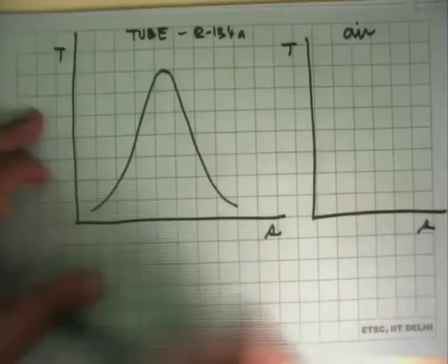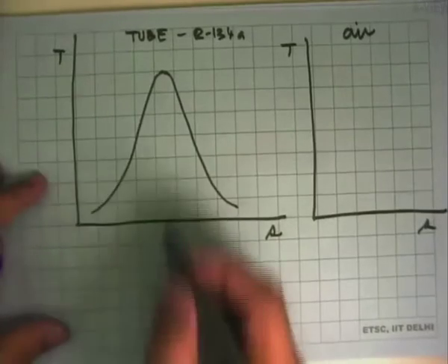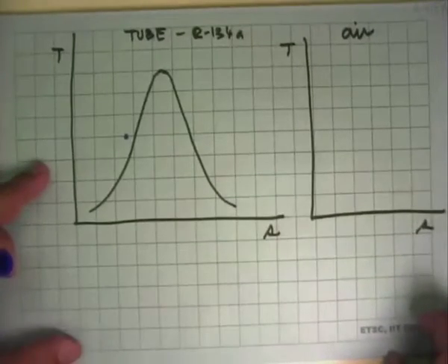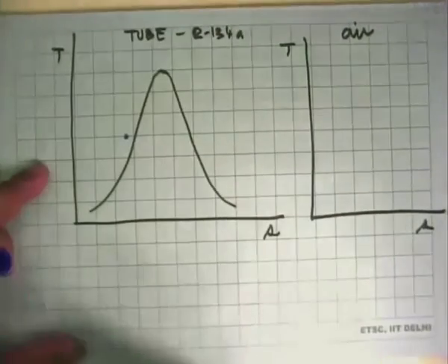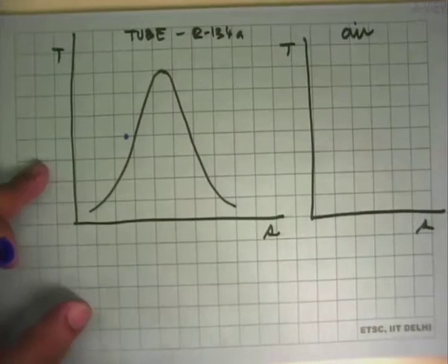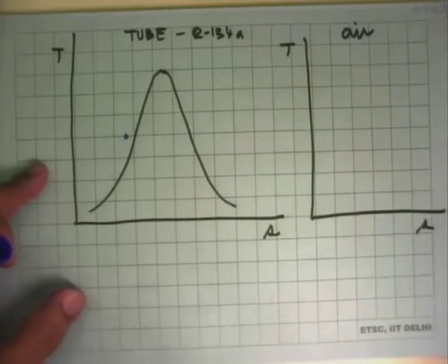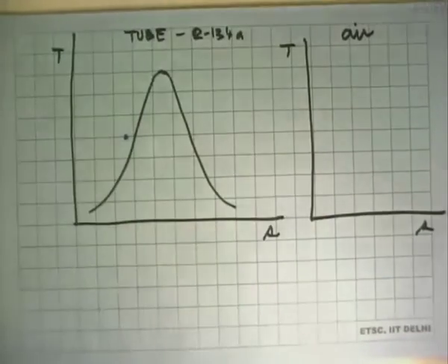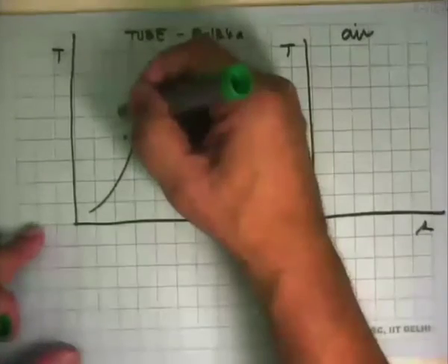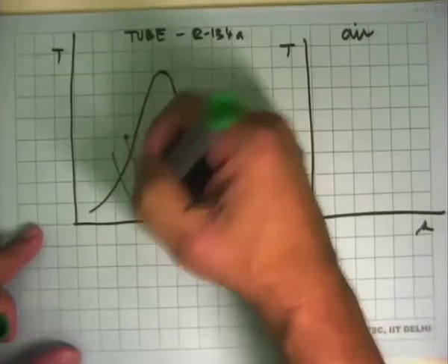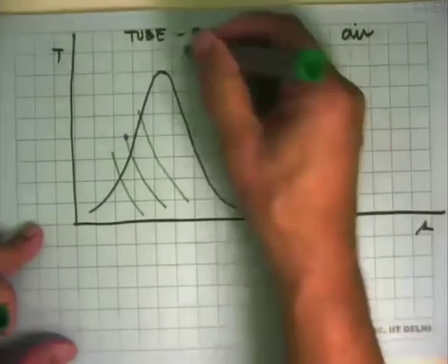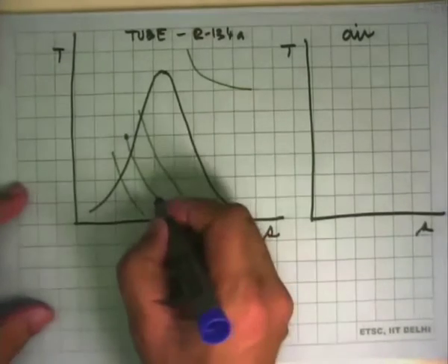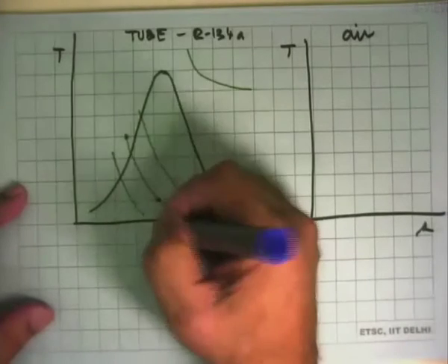So in this case, what is happening is at the end of the condenser, we got slightly subcooled liquid, and this was throttled. Now, throttling is a highly irreversible process, so we don't know what states happen in between. But at the end, we know that enthalpy doesn't change, so it will follow a constant enthalpy line. The constant enthalpy lines on a TS diagram look like this. So the inlet state to the expansion valve was there, and the outlet state was there. In between, we do not know what happened.